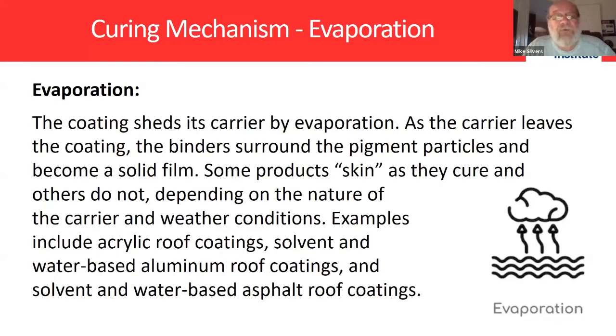If you go to the roof and get a heavy enough rain, you'll have a great big white cloud coming out of where those drainage points are. And you'll end up getting visits from people you don't want to visit you. Because particularly with condos, there's somebody watching every move you make. The minute something goes astray, they're going to be on the phone to somebody, and the next thing you know, somebody's showing up and telling you you've done some damage here. And then your boss is going to get unhappy. So make sure if you're going to put down a water-based coating, you've got enough time for it to cure.